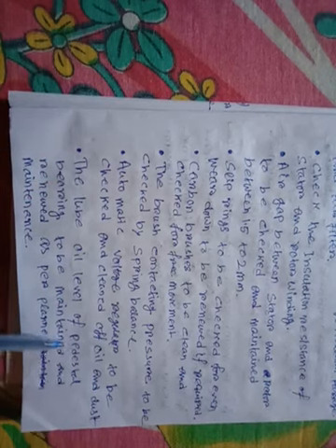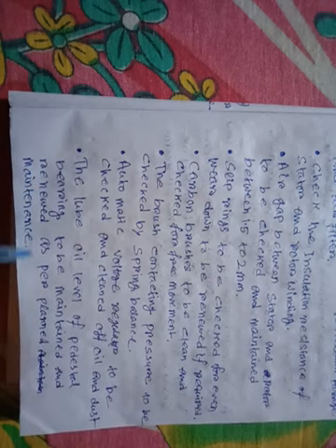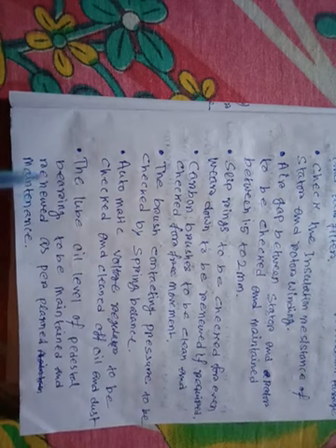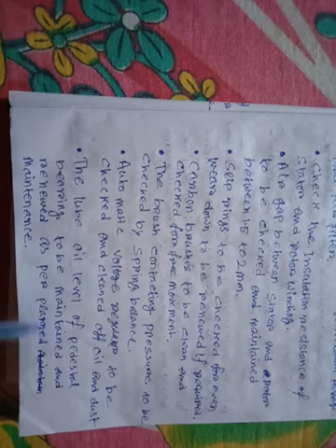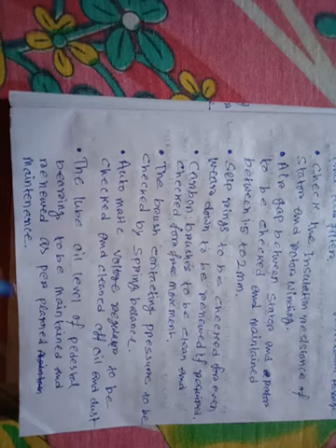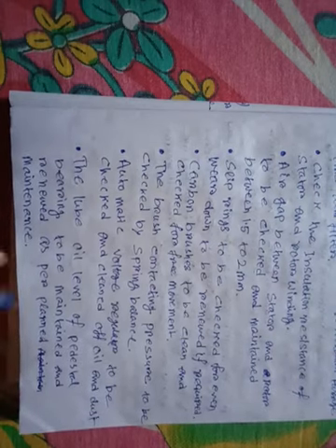The lube oil level of the pedestal bearing is to be maintained and renewed as per the planned maintenance. The lube oil is provided to the bearing for free moving. At this time, we should check the oil level of the bearing.